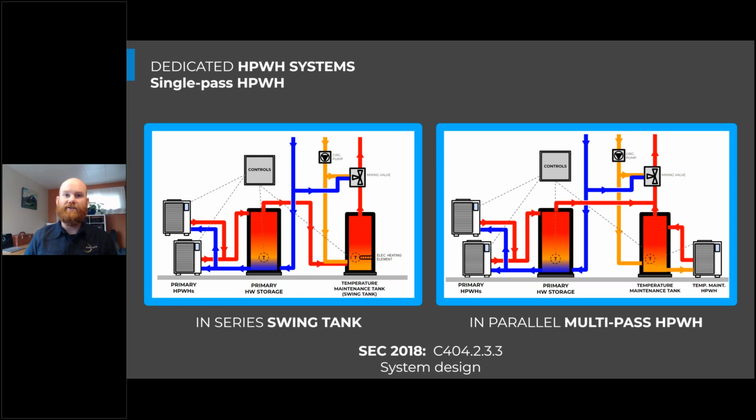Yeah, great question. So it's more on storage tank design. Typically when it fails, I don't think I've ever personally run into that, but I would imagine if it failed, the system would need to be shut down, and you'd need to pipe around that tank, or be able to provide a tank in a timely manner, so that you can get that system up and running again. That is one advantage. If you have parallel tanks, you can essentially shut off one of those parallel circuits.